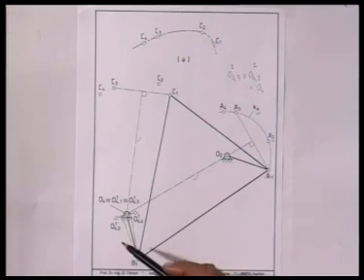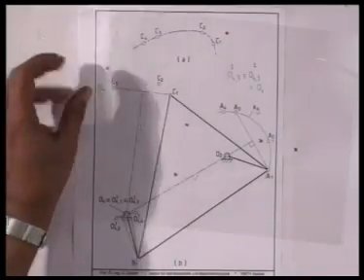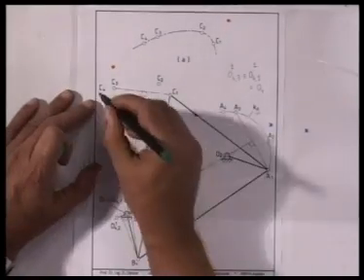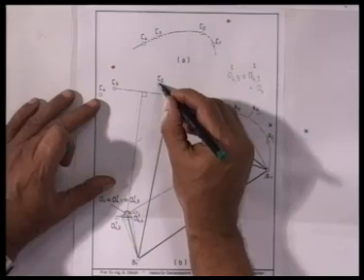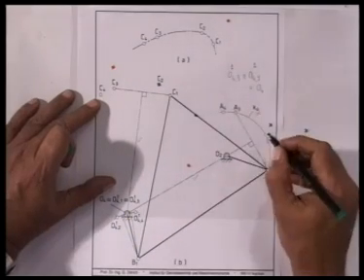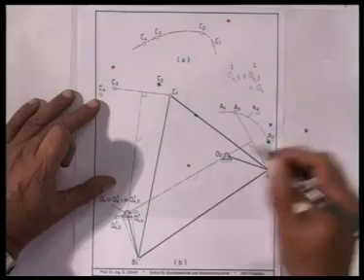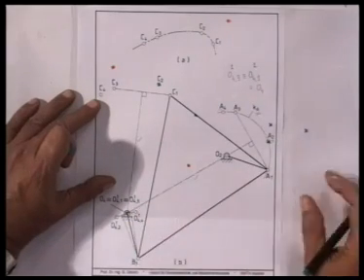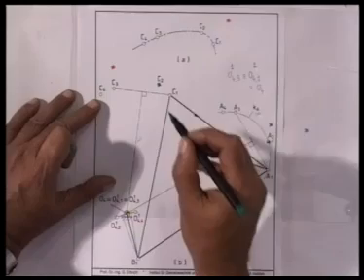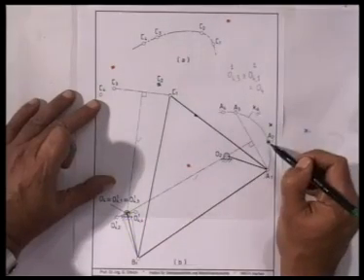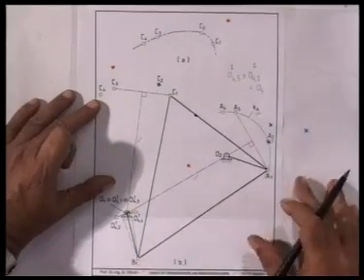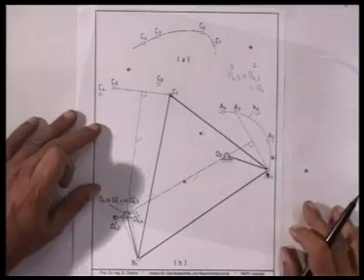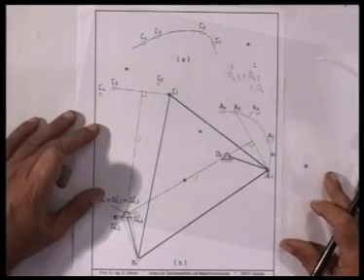Next we determine where is O4,2,1 and O4,4,1. To do that, we follow the same procedure of kinematic inversion. I mark C2, A2 and O4. This is C2, this is A2 and this is O4. So I make C2 coincide with C1 and A2 coincide with A1.